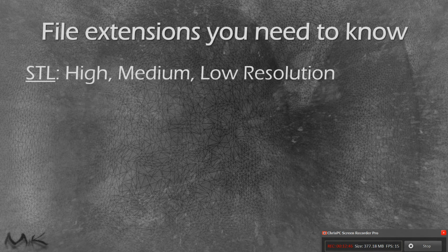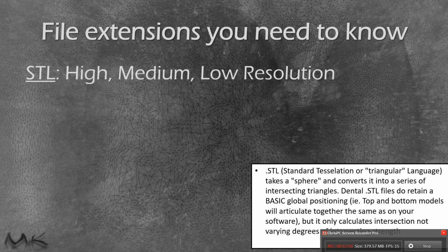So when we say STL, STL actually stands for something called Standard Tessellation Language. And within that standard tessellation language, we have high, medium, and low resolution. What STL files do is it takes a sphere and it converts it into a series of intersecting triangles that creates these things called facets.